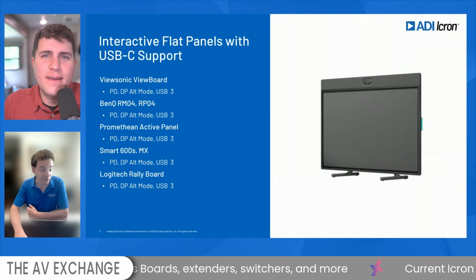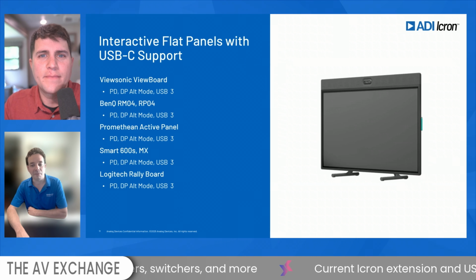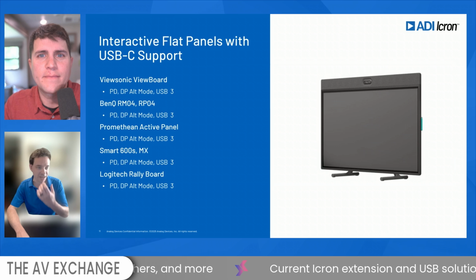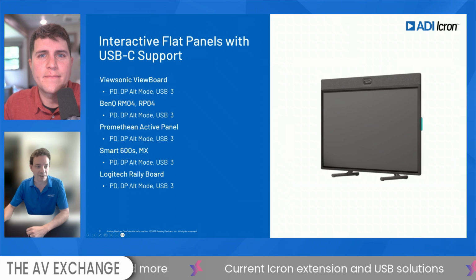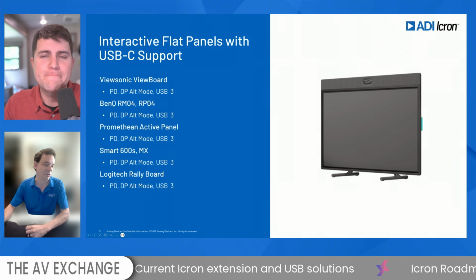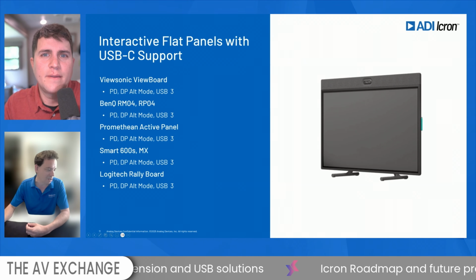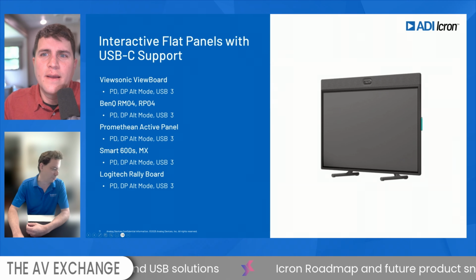And you got your fancy boards. These are all pretty consistent, I found. Every application for these interactive flat panels or boards, they'll run Android, and I guess the cost is enough that they can just fully feature these Type-C cables. So they all can do power, they all do the video, and they all do USB 3. So you're pretty safe on this category. There's not much variation, not like the all-in-ones.